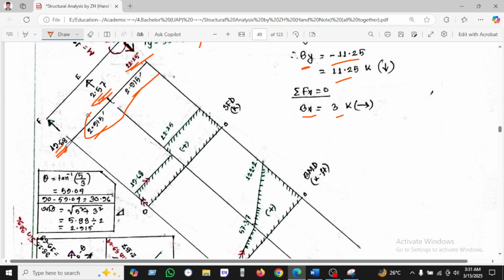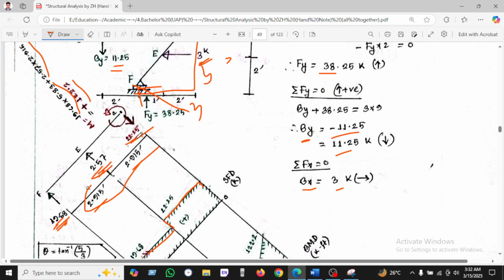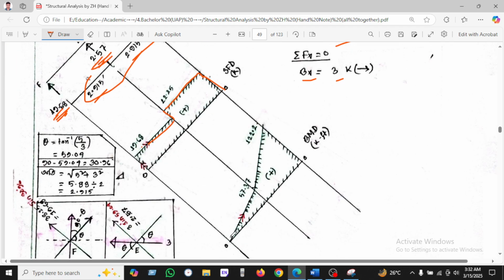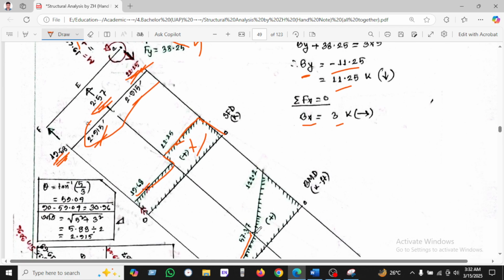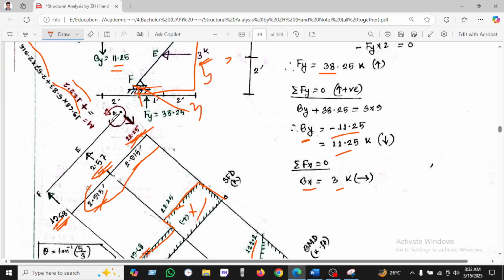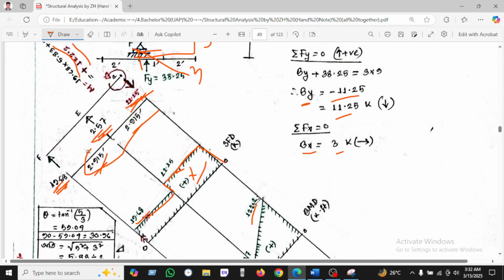So now draw the shear force. Here in the shear force diagram, as we've been seeing, the upward will be 19.6 and there is no below, it will go there, and upward is also 2.57 and 22.2, and there is another downward 22, so this will be 0. So we've been seeing here the 19.6 into 2.91, so it will go there as 50.57, and it will be positive. Then adding this value we found 22.2. Now we're deducting the negative balance, it will be downward and it will be 0.